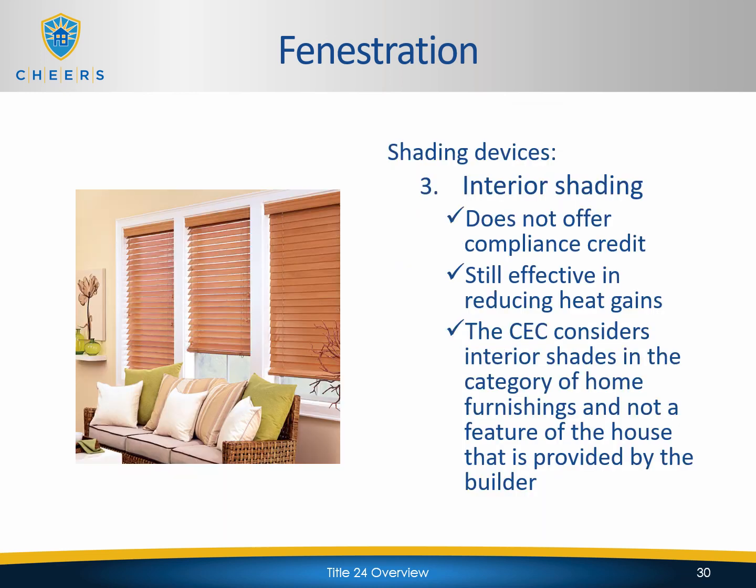Now interior shading, so now we're talking about blinds, shutters, whatever it may be. It doesn't offer compliance credit. It's still effective in reducing heat gains. However, like I said, it doesn't count for Title 24. The CEC considered interior shades in the category of a home furnishing and not a feature of the house that is provided by the builder. And because for the most part interior shading can always be moved, removed, changed, and so forth, it's not really a permanent fixture. Therefore, it doesn't give Title 24 compliance.